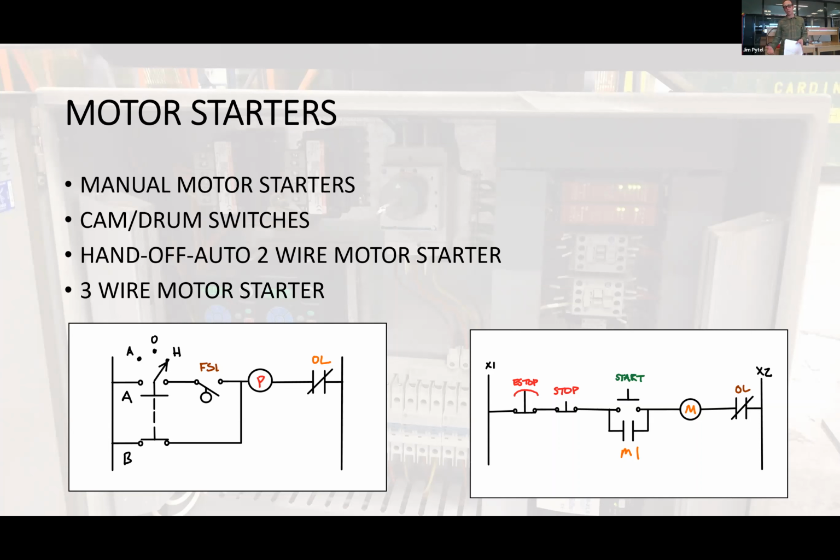So now go over to the 3-wire circuit. In the event that that motor overloads, that normally closed overload on the right opens up and stops the motor, and the holding circuit drops out. If that overload was to cool, it would close, but the motor won't restart.